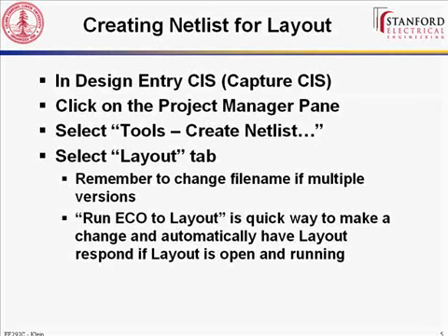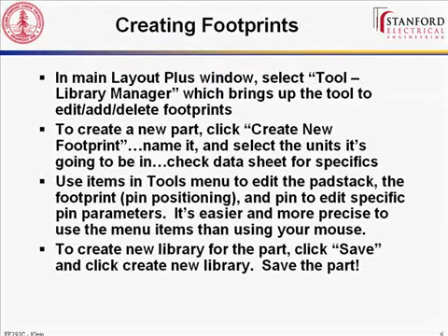So the next couple of slides are basically written tutorials of what we're about to do. The first thing that we're going to do when you actually do a layout is create a netlist. The netlist is created inside of Design Entry CIS, and it basically is a file that has a listing of all of the nets you've created, so all of those lines you created in your schematic, and of what nodes or what parts are connected together through those nets. Again, we'll go through this in an actual demonstration, but this is so you have a written copy somewhere.